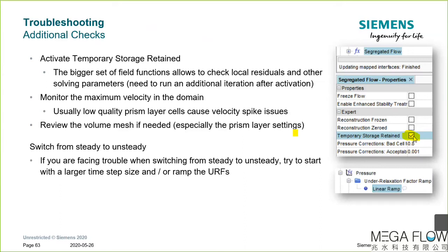So most of the time, to be honest, I don't do that. So I switch directly from steady to unsteady with the fine time step size. But maybe with the coarser time step, you can also speed up washing out the steadiness.